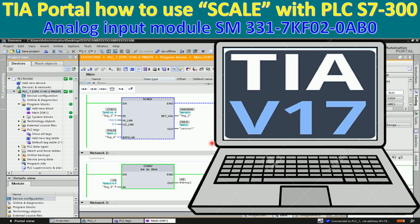Today I would like to show and share how to use TIA Portal version 17 and how to use the scale with the PLC S7-300. In this section, I will use the analog input module SM331 7KF02-0AA0 to test with the scale.